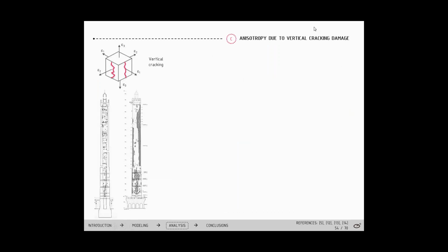So jumping to the C group of analysis mentioned before, it is safe to say that there are many and very thorough masonry anisotropic models in the scientific literature. However, these models are typically based on the fact that the anisotropy is caused by the heterogeneous disposition of bricks and mortar and have the purpose of transforming the mesostructure in a continuous anisotropic model through homogenization processes.